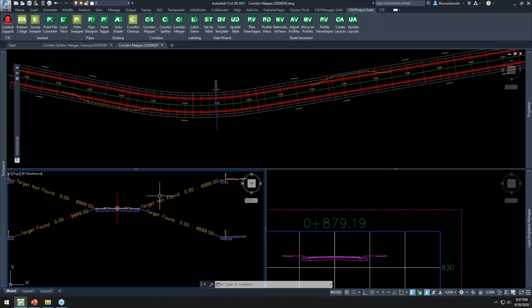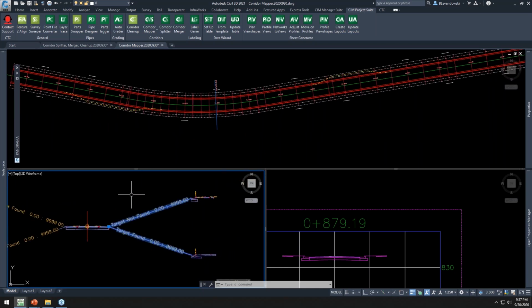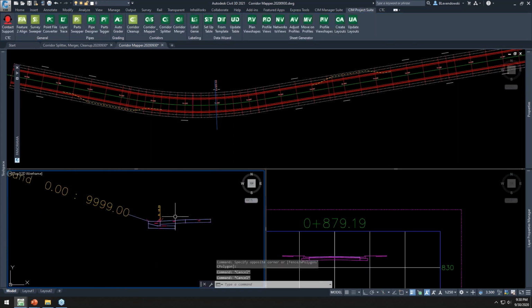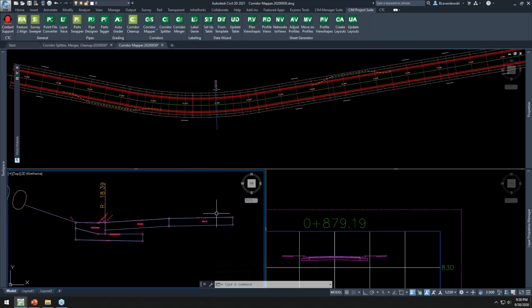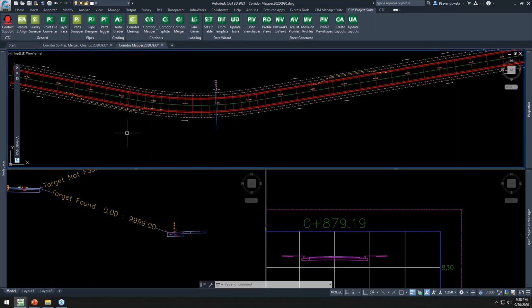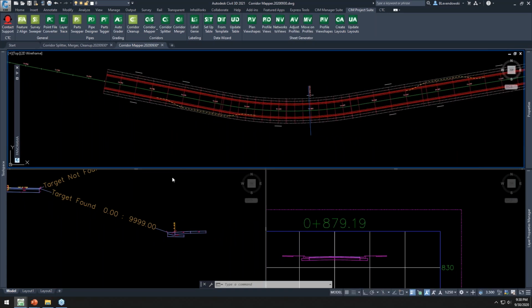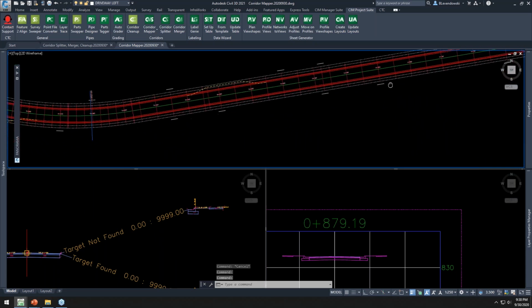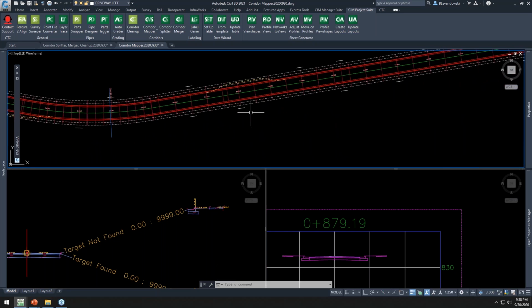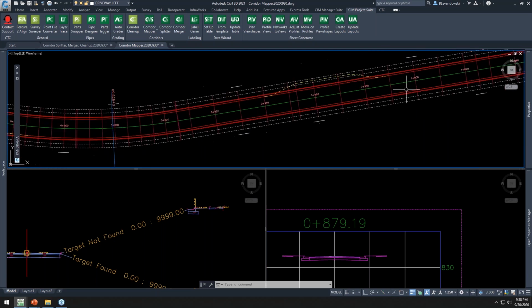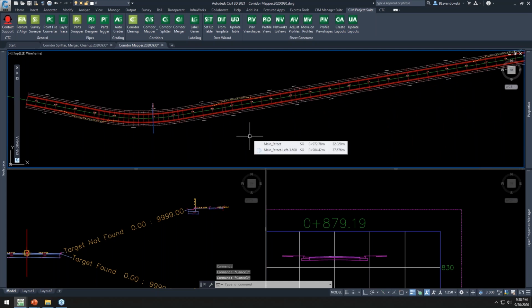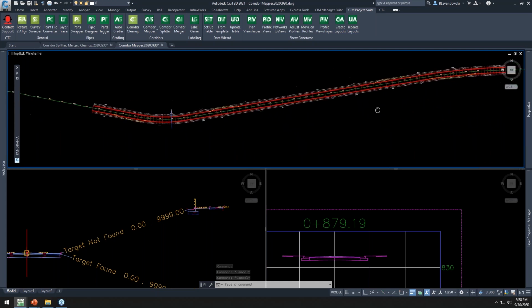And so I've got a scenario here where I'm using just some native conditional subassemblies to be able to switch between standard curb and sidewalk and a drive over curb and a driveway. So pretty common in road reconstruction projects. And of course, with conditional subassemblies, what you simply do is draw these little polylines or lines to represent where all those driveways are, assign the targets and so on, right? I've also got a number of offset alignments here representing parking lanes. Okay, so a pretty target intensive little sample of a piece of a project.